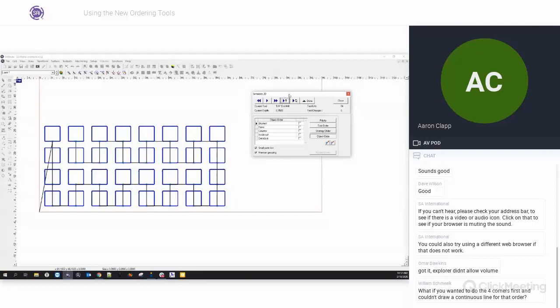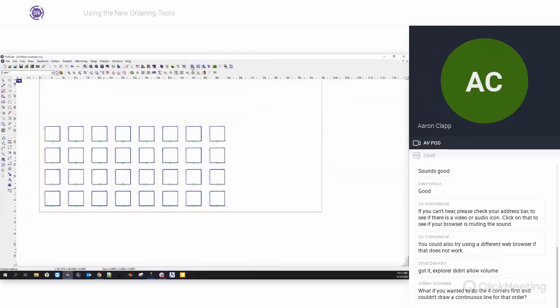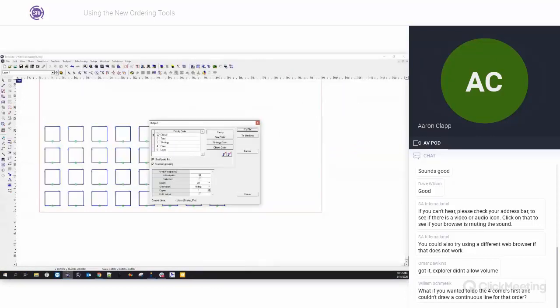So you want to make sure and save this to a preference. If you make any changes in the Simulate 2D, my default thing to do is I just hit this little P with the arrow pointed to it, and that'll save it as a preference so that when I hit close and done, and I actually go to my output screen, objects is still at the top, it's still unchecked, and all I have to do is hit to file.